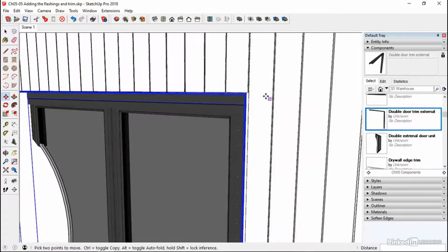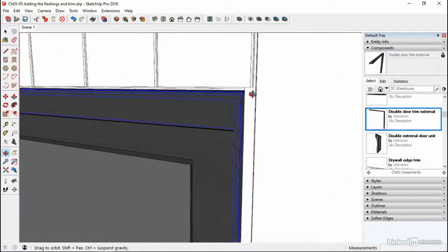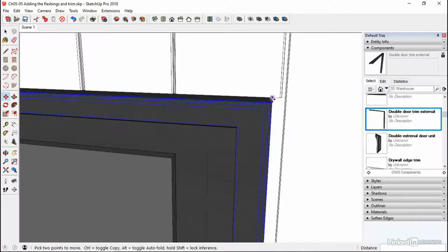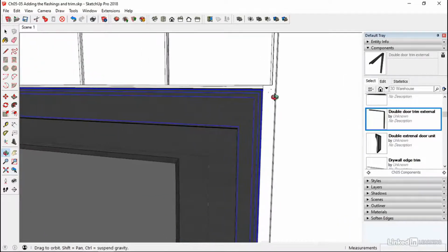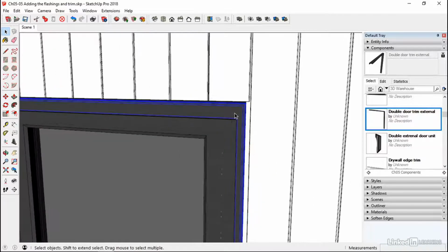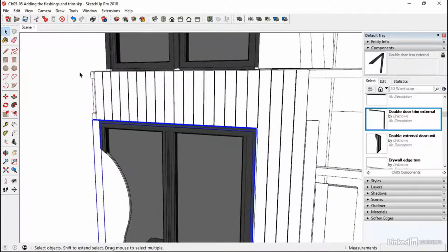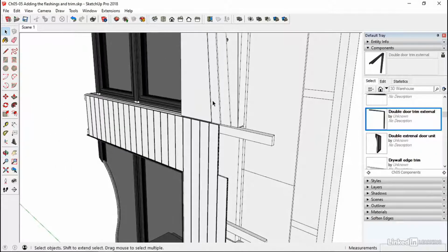And then we get a nice little junction at this point. Then we could possibly take this over a little bit. We might also think about trimming off the tongue of this one, or work out a slightly different way of doing it. Okay, so maybe we take that back and line this a bit closer in. Again, the fact that we've got this level of detail gives us the opportunities to check these things out at a later date. So up to this bit here, this is the separation point between the board and the screed.